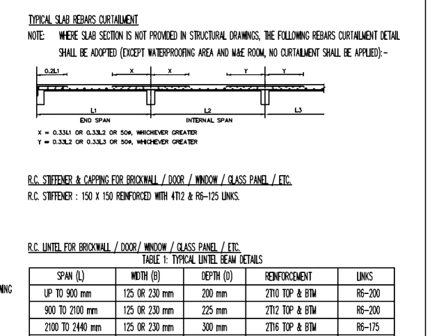Also, you can view this from the perspective of industrial practices, considering the staircase as a typical slab. For a typical slab, these are the recommended curtailments. It is specified here the required length of the curtailment. Let's say for the end span, we are talking about 20% of the end span. The provided anchorage length at the end span should be at least greater than that 20%.